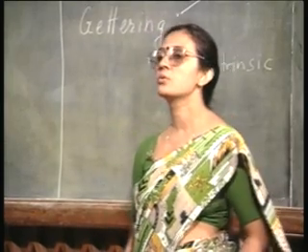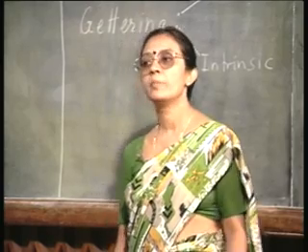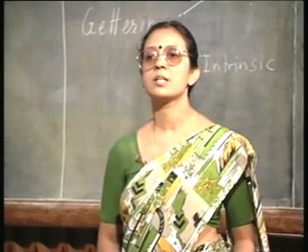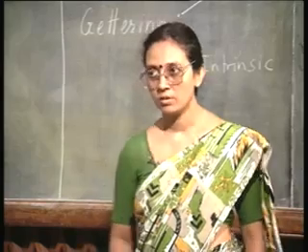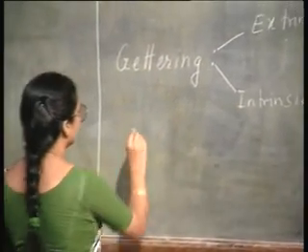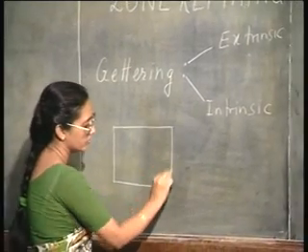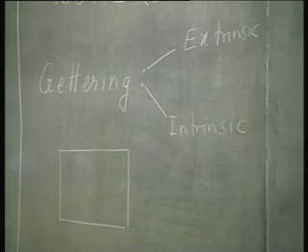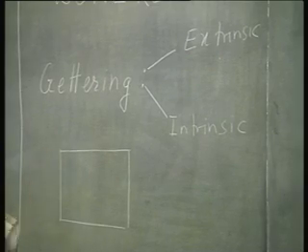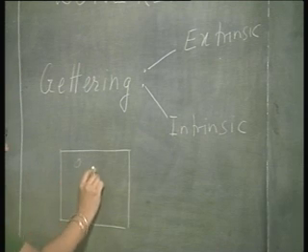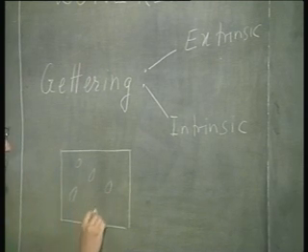But you can use it to your advantage, provided you make sure that such precipitates are not there in the active region. That is what I am trying to say. Suppose this is your wafer cross section. This is the thickness of the wafer, full 500 micron. So, I have these oxygen precipitates all over the place.